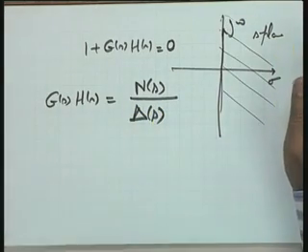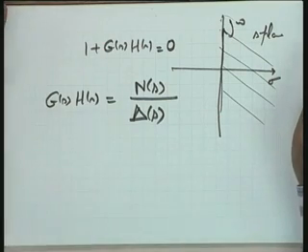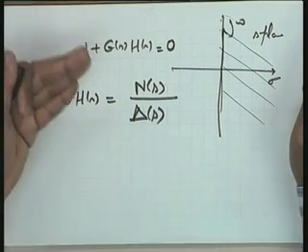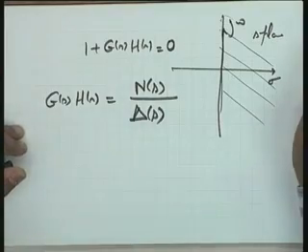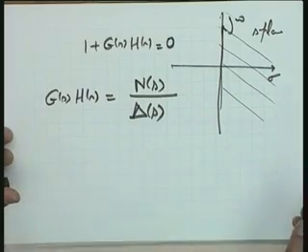And all the G(s)H(s) we have encountered so far are really ratios of two polynomials except the case of dead time, where e to the power of minus s tau d we have taken. So initially for convenience, though the result will be applicable to other functions including dead time, let me take G(s)H(s) to be a ratio of two polynomials, the N(s) polynomial and the delta(s) polynomial.